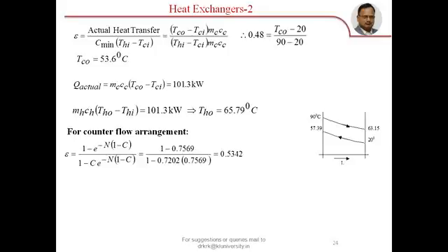So in the simulation of a heat exchanger, when you want to simulate it for conditions other than the existing working condition, the number of transfer units always remains the same. That is the importance of the number of transfer units.